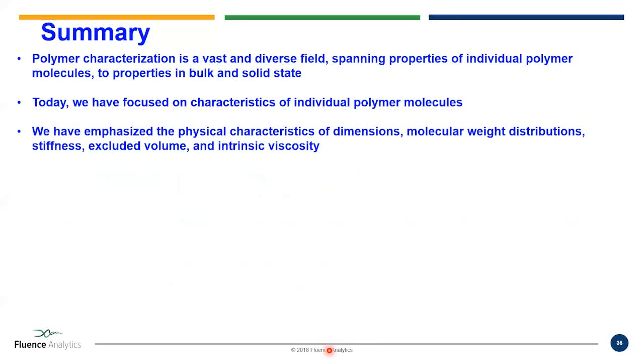I mean, if it's how they're, so we mentioned that the RI measures concentration, and the light scattering measures molecular weight. So in that sense, they're very different. The RI is just going to give you concentration. The light scattering will give you an absolute molecular weight. It does require that concentration measurement, however, so if you have light scattering, you have to also have a concentration detector, whether RI or UV. I think that probably answers it.